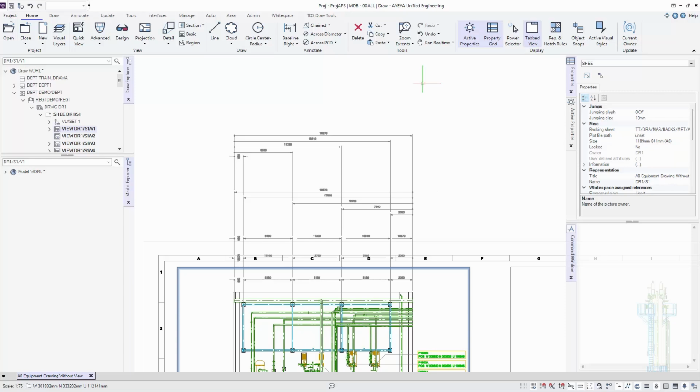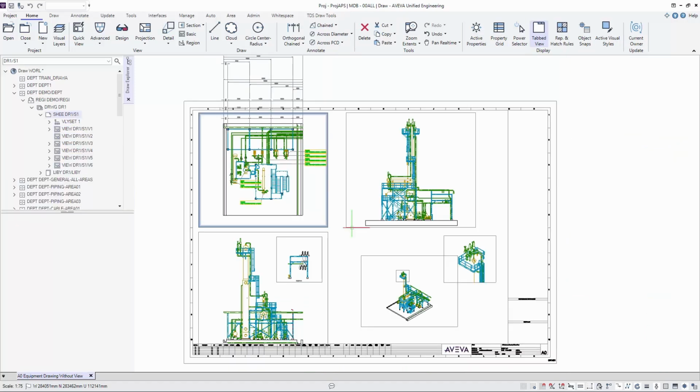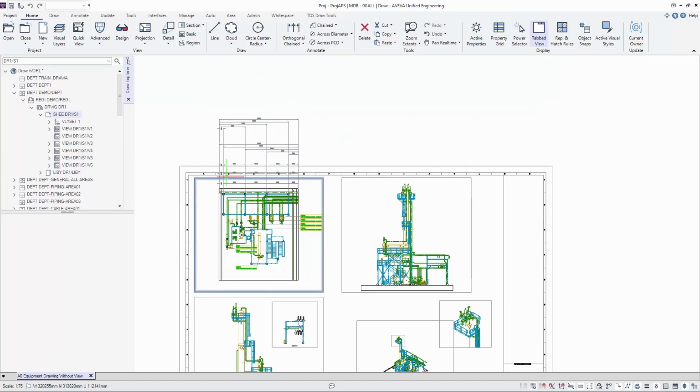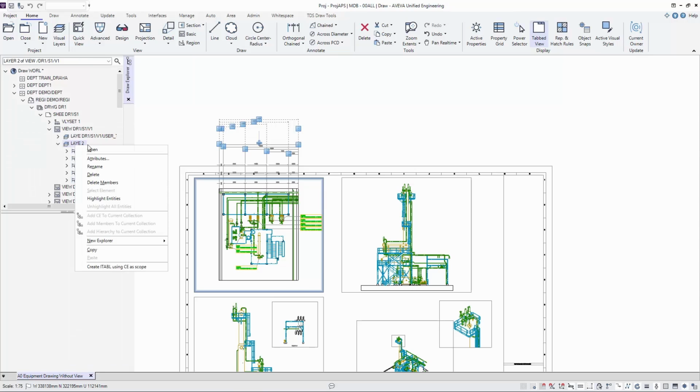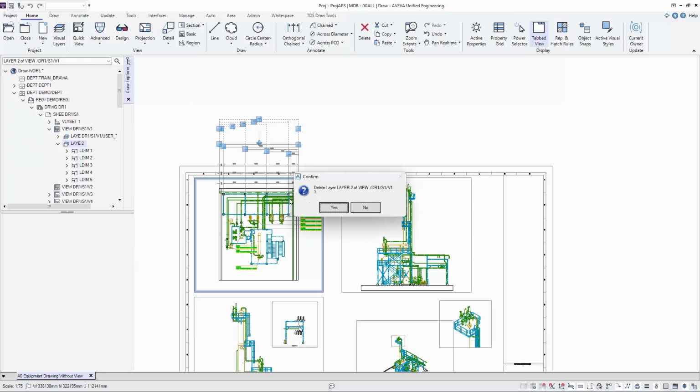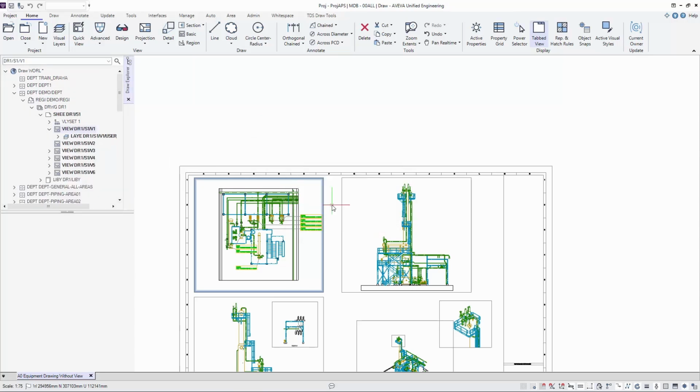Now that we've introduced the different types of linear dimensions, we're ready to begin the lesson proper. In this section, I'll give you a detailed, step-by-step explanation of how to actually create dimensions in E3D Design. Let's start by clearing out the dimensions that we created earlier. To do this, I use the Draw Explorer, navigate to the Dimension layer, and simply delete the layers.